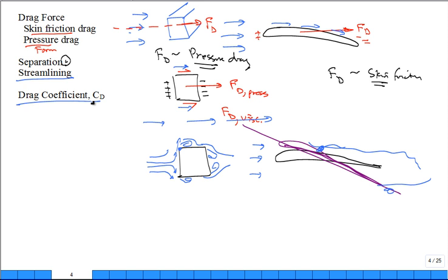What about our drag coefficient? Well, our drag coefficient, we learned from our non-dimensionalization, talking about Buckingham Pi theorem or algorithm, determined relationships. Often you have the relationship that the drag coefficient is a function of the Reynolds number. We did that before, so we're going to use that. We know that's our strategy.